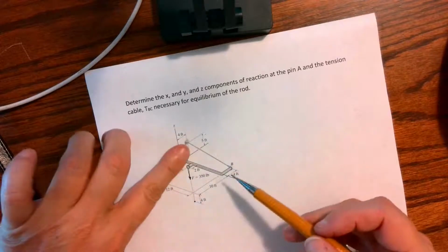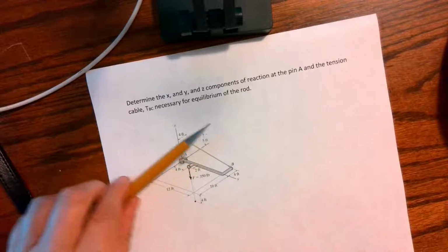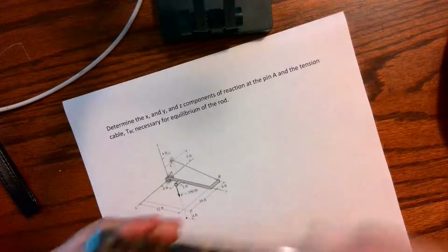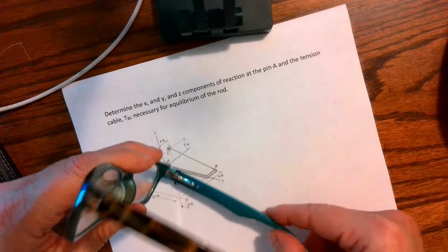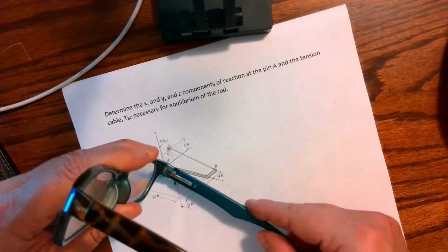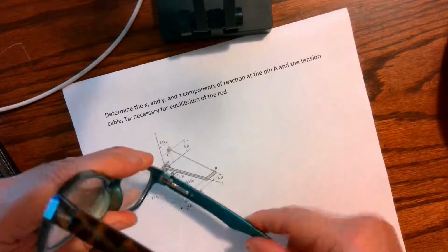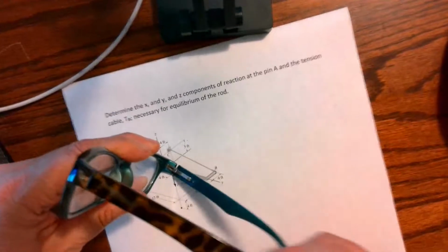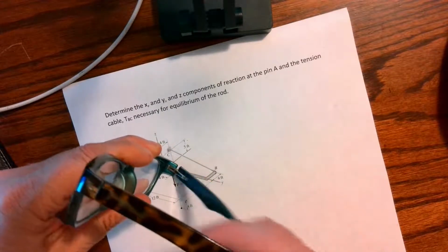The only thing that would happen is if I'm looking at the x-axis, here's my x-axis, and I pushed up here at B, it's going to rotate. So it's much like the pin if you have a pair of glasses, okay? It's much like this pin. It is not going anywhere. X, Y, Z, I can't pull the earpiece off. I can't rotate it around the Z. I can't twist it, torsion around the Y, but if I push up, I have nice rotation around that x-axis. So I develop every force except rotation about the x-axis.